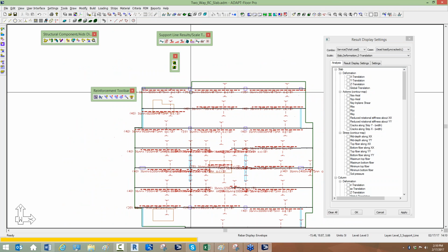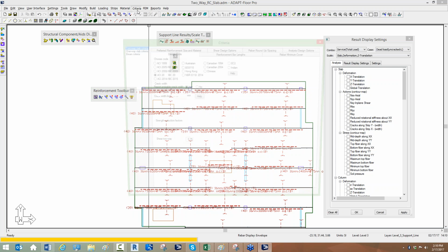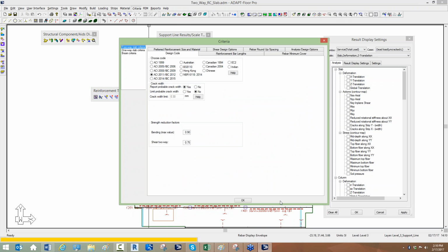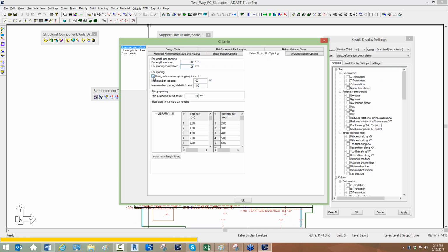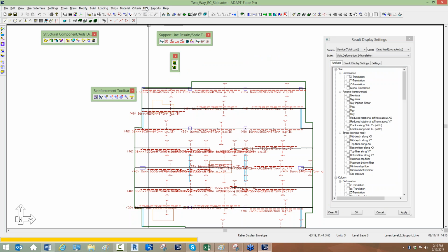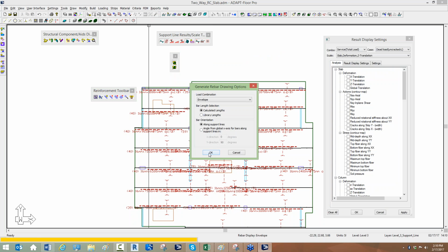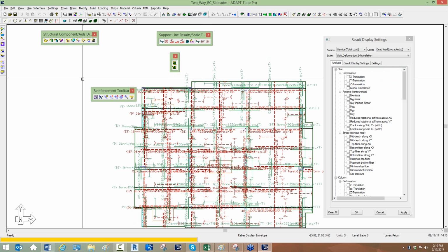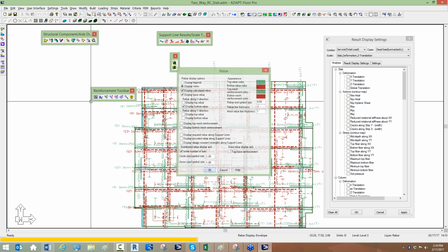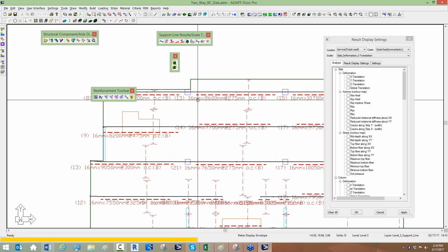So that's important because we get a lot of questions about that in support. Why does my rebar look different here versus here? And this is typically the reason for an RC slab. So if I just say, well, I know I'm either going to have a rebar mesh in the slab, or I'm going to meet that minimum spacing requirement somehow, I'll just turn off the bar spacing, and if I regenerate the drawing for reinforcing, and I reset the view back to bottom in the X, I'm back now to my 13, 16 millimeter bars. So there's a question here.